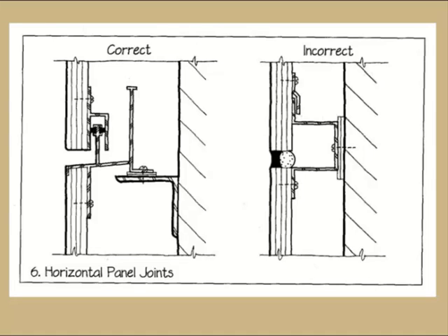Although this will obviously hold the materials in place, the difficulty with this type of system is that as soon as that sealant joint fails with time, and they will fail with time, you get leakage and there's no backup system for it. The system on the left will also provide the structural support, but it incorporates a sloped surface so that any water that comes into that can drain back out.